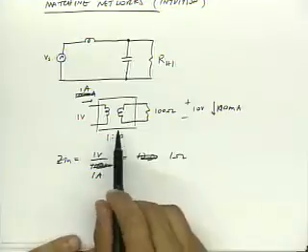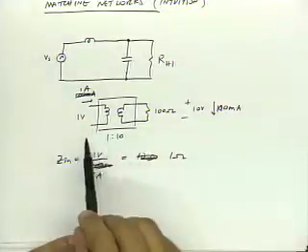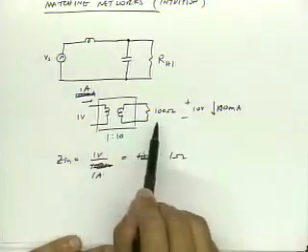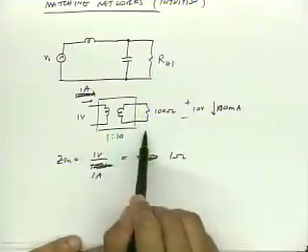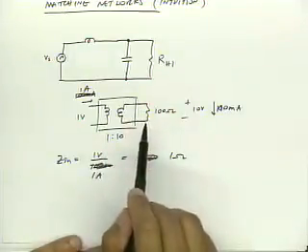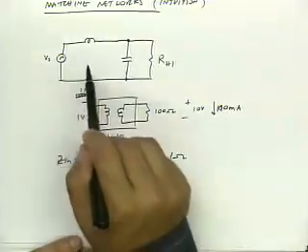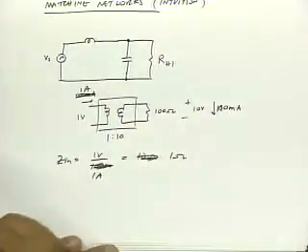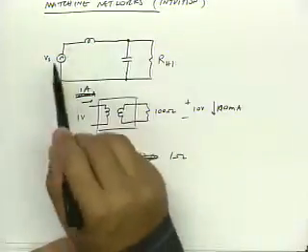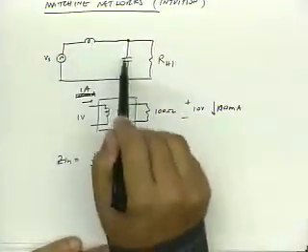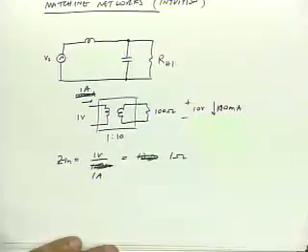So what's happened in this circuit is that I've multiplied the voltage when I've applied it across here. That did the magic trick. In this circuit, if I think of this as a series circuit, then I can also produce voltage multiplication across a reactance, right?